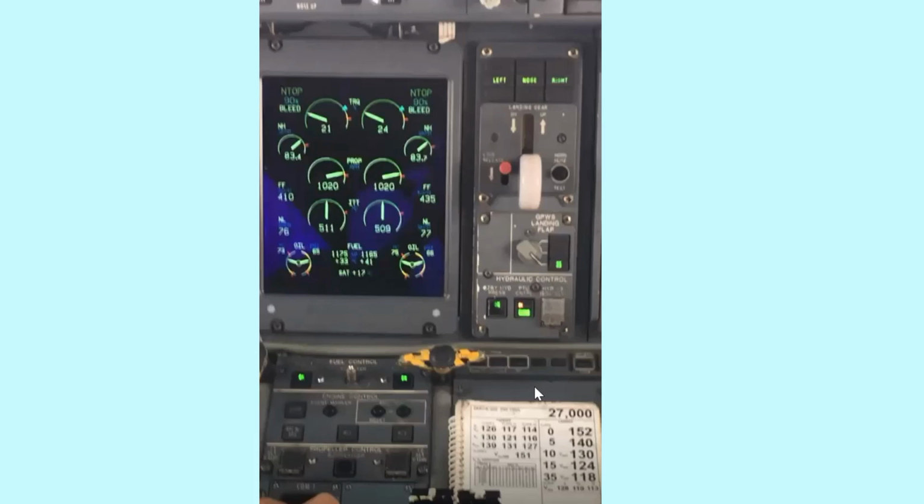When we maintain that same configuration with the autopilot and flaps 35, we will see that for us to maintain Vref to Vref plus 10, somewhere around there, the torque value which we set here roughly equals that value. So it's not a magic figure, as some people may call it. It is actually happening because the autopilot does this, or makes us do this, when you are doing an autopilot approach.